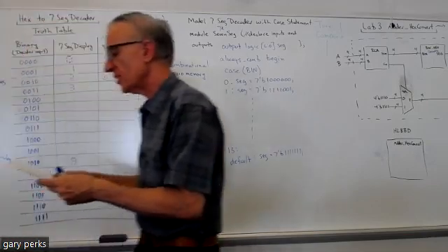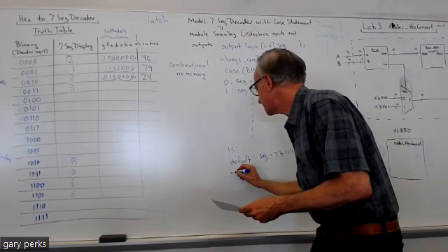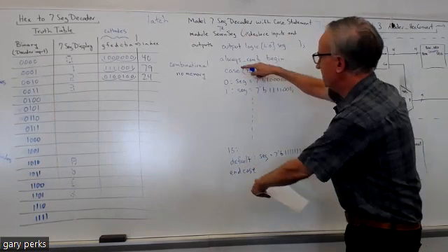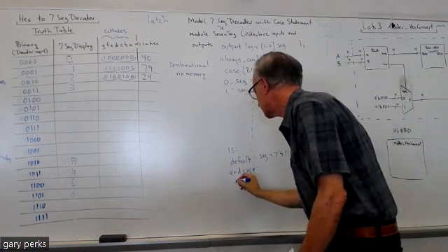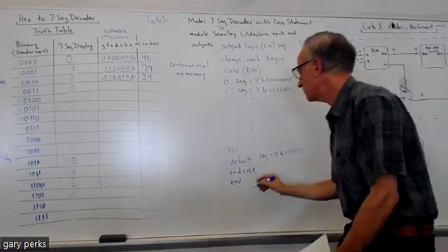Okay. All right, but to finish this, after the default, you would end the case. So you have end case. That ends the case, and then you want to end this begin, which is the always block, so you have an end for this begin, and then you end module.